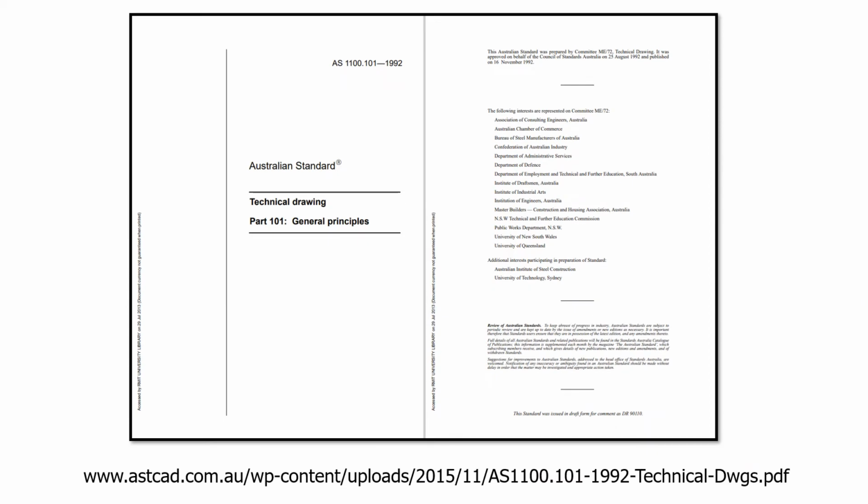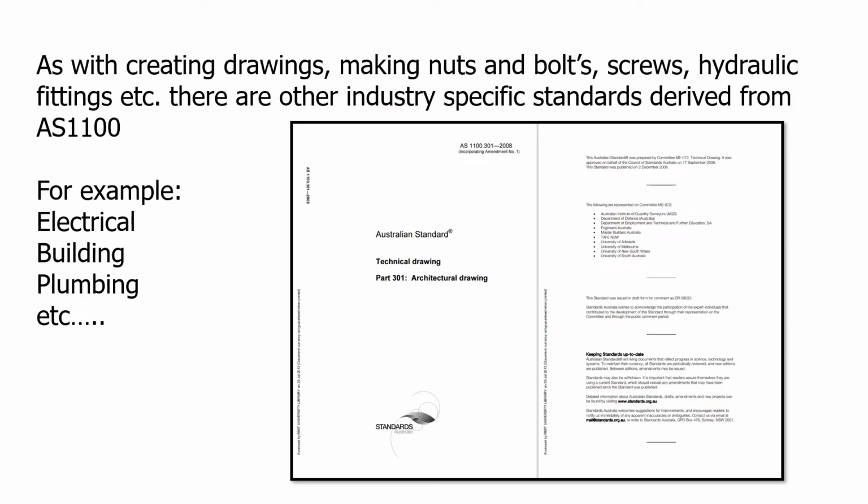As well as the textbook, another great resource for creating or interpreting engineering drawings is to get a copy of the Australian Standard. It's not surprising that there's a standard for creating engineering drawings. The Australian Standard is AS 1100. AS 1100 is a drawing standard that is used within Australia. It defines every aspect of the drawing. AS 1100 provides a standard that allows for clarity, understanding, and uniformity across all drawings generated nationwide.